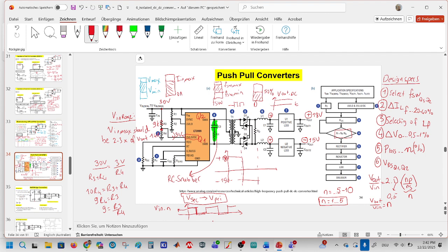Or under voltage, we define the minimum voltage as, let's say, 10 volts. 10 volts would mean R1 plus R2 is equal to, let's say, the minimum value in the controller should be 1 volt, and the ratio of R1 to R2 is again 9 to 1.